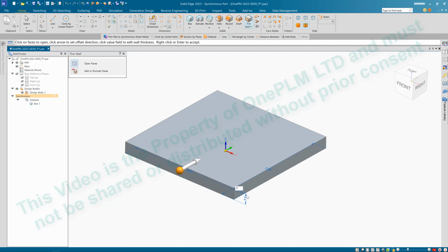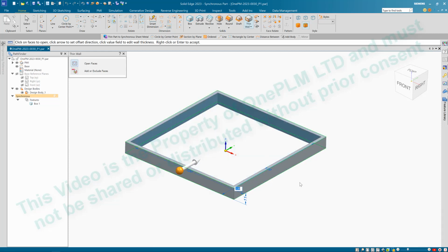So if you press 3 and tab, so use the tab button to give you like an enter on the preview. So rather than confirming it, it's asking us to select the open faces. If we click that face and click that face, we could spin around and click the underside face, but it doesn't matter. And then right click to accept. So that is our enter on there.